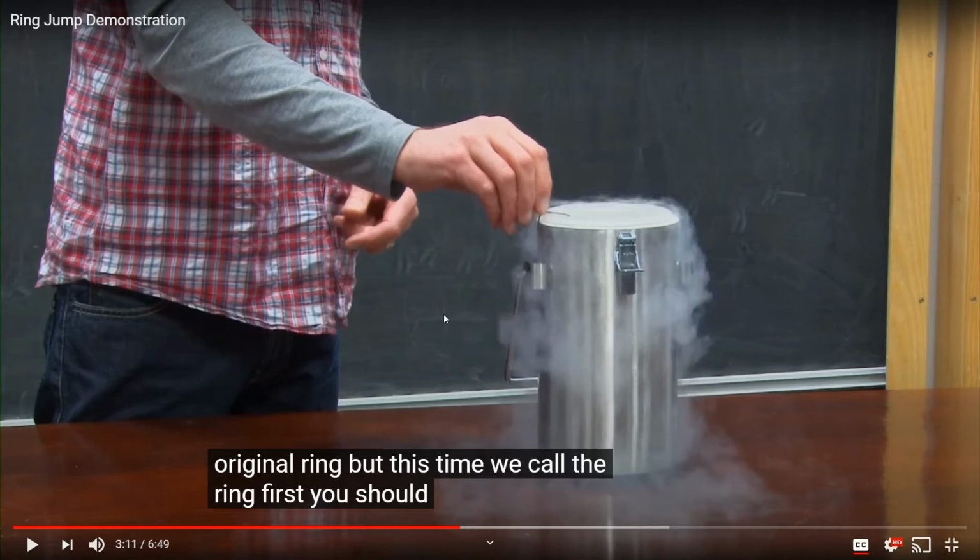So one way to think about it is that that gap introduces a huge amount of resistance to the ring, because in order for current to flow, you'd have to have a spark that would flow across the gap. Does that make sense? You'd have to have a spark that could jump through the air, and the resistance of air is very high. So that's one way to think about it. The easier way to think about it is dielectric breakdown. That's what it's called when you get that spark. But the other way to think about it is just, if there's a gap, you can't have current, basically. There's no way it's going to flow.